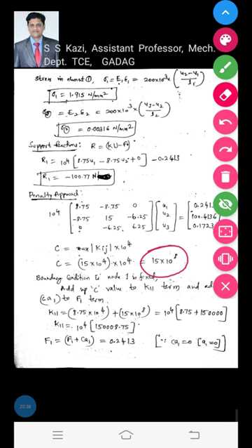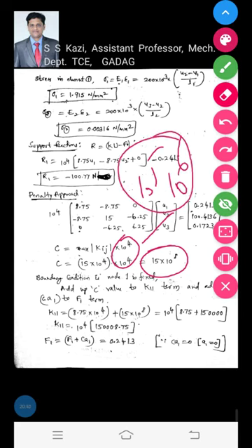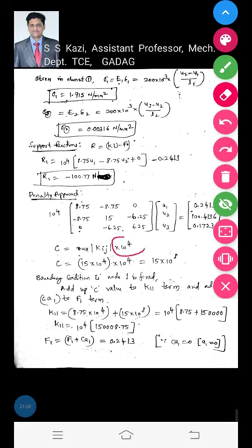This is how we have to calculate the stiffness value. The 10 raised to 4 is the experimentally found correct value. You may go for 10 raised to 5 or 10 raised to 6, but these are not experimentally found correct values, because they will not give an accurate result. Hence, 10 raised to 4 should be multiplied with the maximum of Kij. We got 15 into 10 raised to 8.